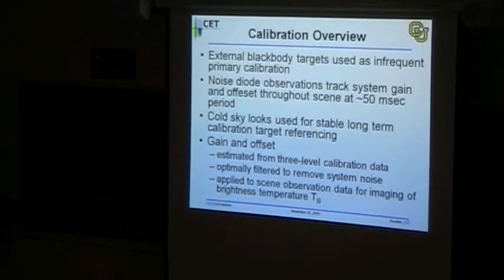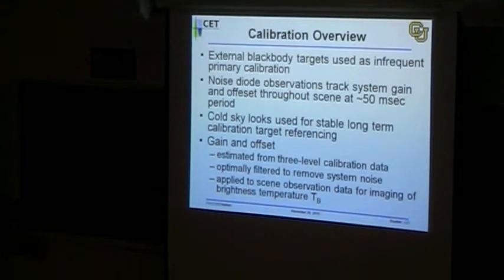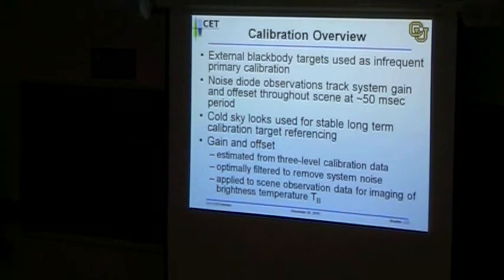How much overall energy does this receiver take in? Well, it typically takes in not only the Earth's terrestrial temperature, the equivalent energy of that, which is around 300 Kelvin, give or take, but also it takes in energy from its own little receiver in the form of additional noise. And that overall amount comes out to the equivalent of about, again, anywhere between 500 Kelvin or so for a good receiver, maybe up to even a couple thousand Kelvin.